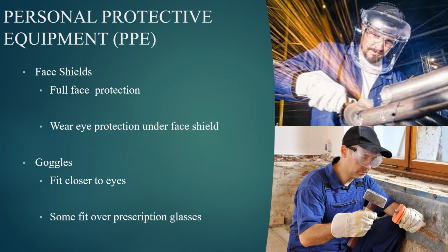Full face protection is often required to guard against molten metal and chemical splashes. Face shields are available to fit over a hard hat or to wear directly on the head. A face shield should always be used with other eye protection, such as goggles or glasses.